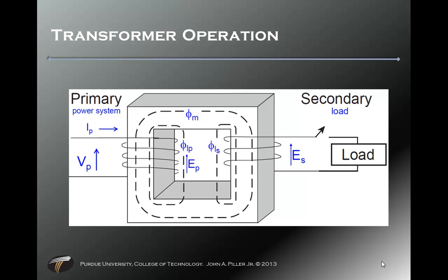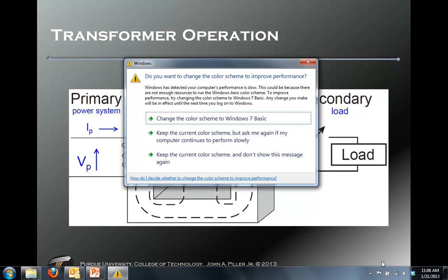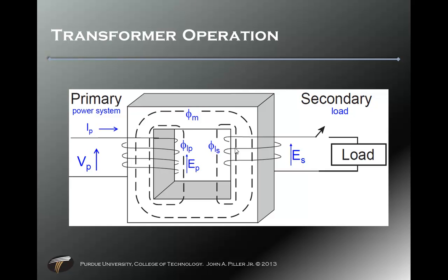Primary power comes in there on the left. Vp causes the primary current, the I sub P, to flow into the coil on the primary. That coil induces a flux. That flux is the phi there, and it creates a voltage essentially there. That voltage and phi rise and fall because we use transformers with an AC current.